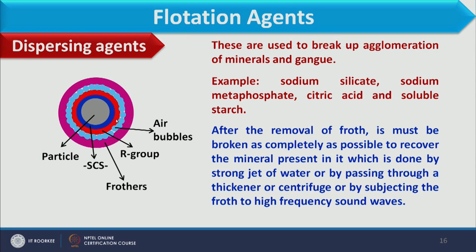Now, once it is floated off, we have the froth. After the removal of froth, it must be broken as completely as possible to recover the mineral present in it, which is done by a strong jet of water or by passing through a thickener or centrifuge or by subjecting the froth to high frequency sound waves.